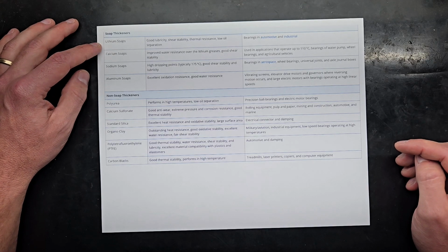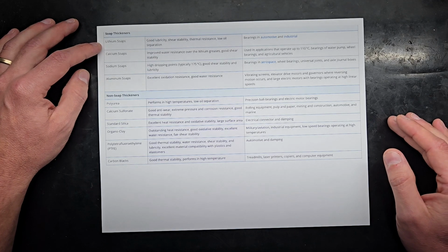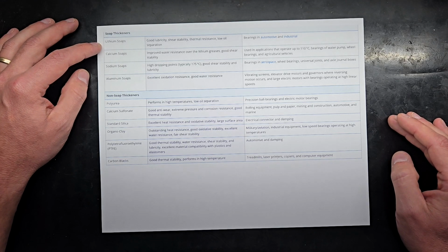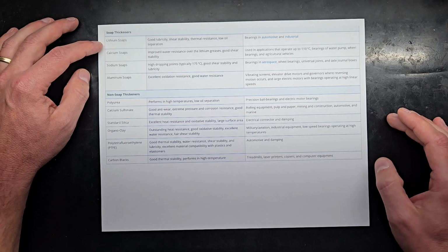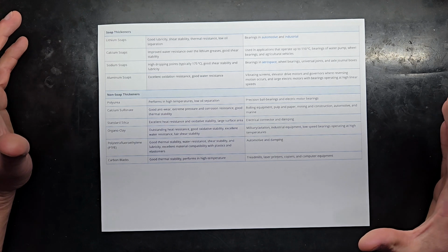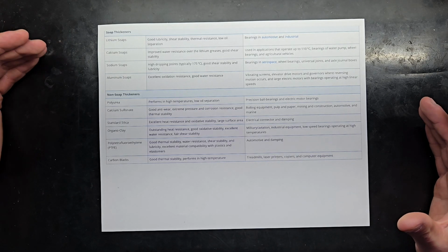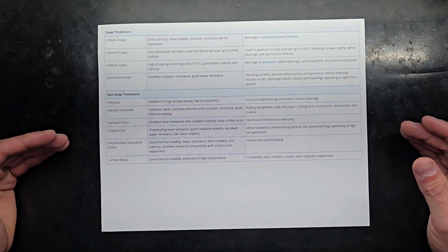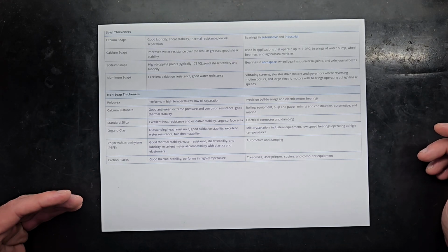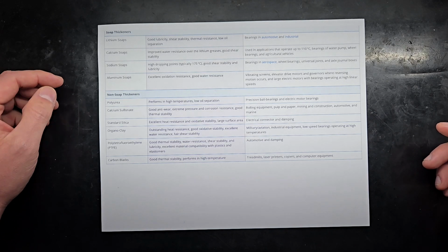Many lithium greases are going to be made with probably about a group 2 base oil. If you're buying a lithium grease that is a fully synthetic grease, they're actually going to be using a naphthenic base oil, so one of those group 5 base oils that is still derived from our dead dinosaurs. So there again, when we refine the crude oil, we've got our paraffin structures, our naphthenic structures, our aromatic structures, and the fourth one escapes me because I don't have my book to cheat off of right beside me. And so that naphthenic structure can be pulled off, and there are base oils made from that.